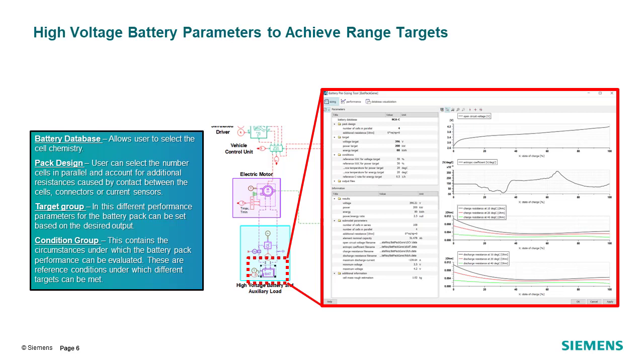Voltage and energy targets. These parameters can be refined from different tools available from the variables window in SimCenter Amesim. We will specifically look at the battery pre-sizing tool in order to tune the parameters.